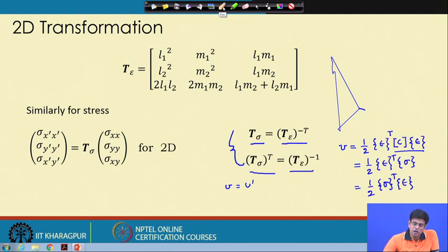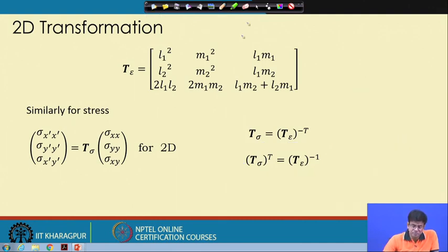Now with this in mind, we can approach what will be the constitutive matrix. What have we seen? We have seen how to transform a coordinate, how to transform a general vector, for instance displacement, and then we transform a second order quantity, essentially written in Voigt format, that is strain and stresses, which have the specific transformation matrix.